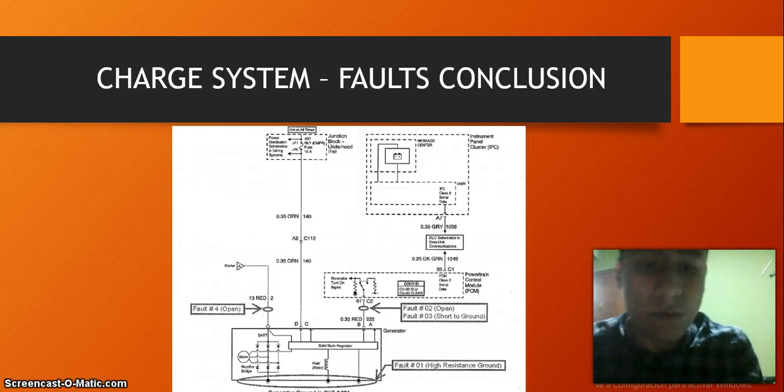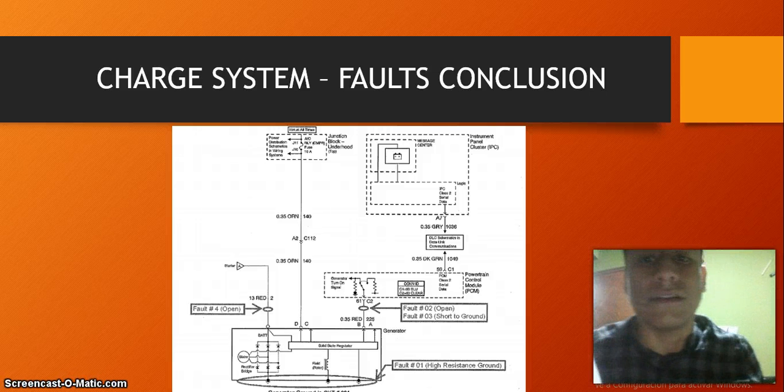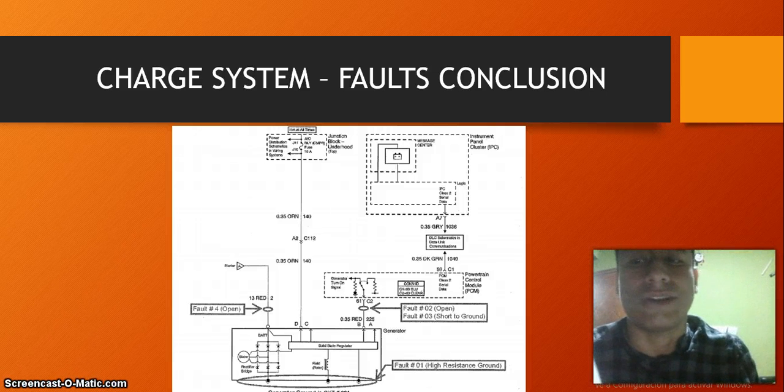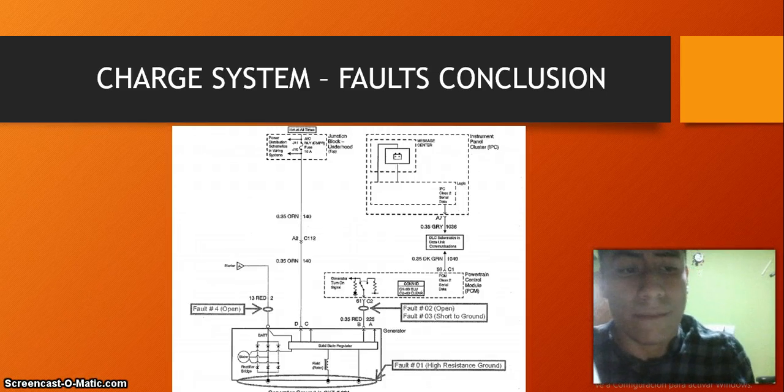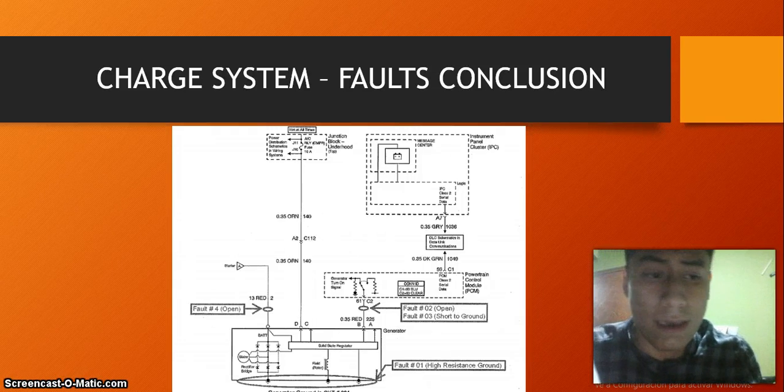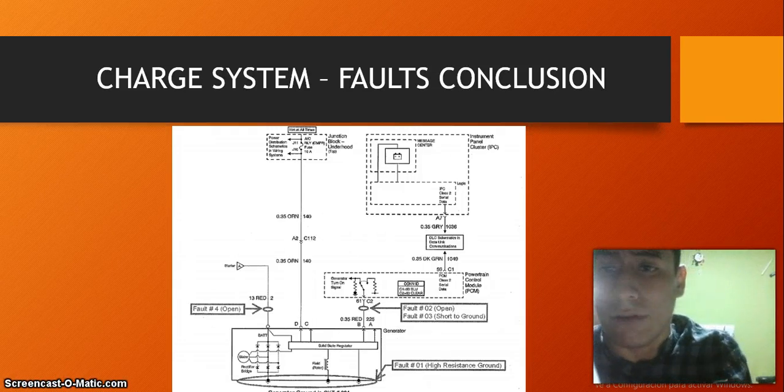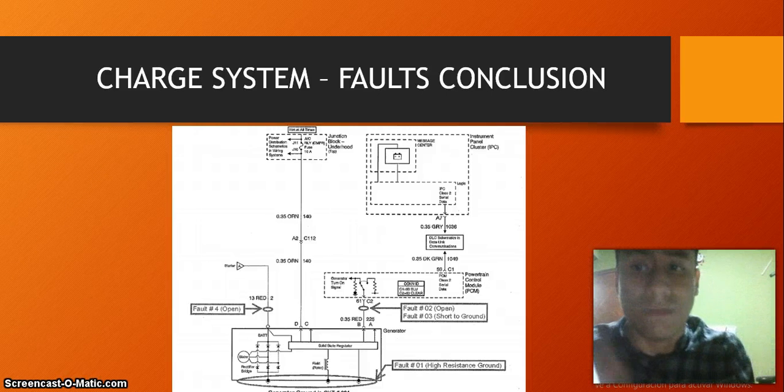In the first instance, it was generally determined that the problem originated due to the malfunction of the alternator, since it did not generate any voltage for the battery charge. However, during the time of the laboratory, the core failure of the equipment was not determined. For which the schematic diagram of the system was reviewed, identifying that the failure occurred due to the high electrical resistance on the ground.